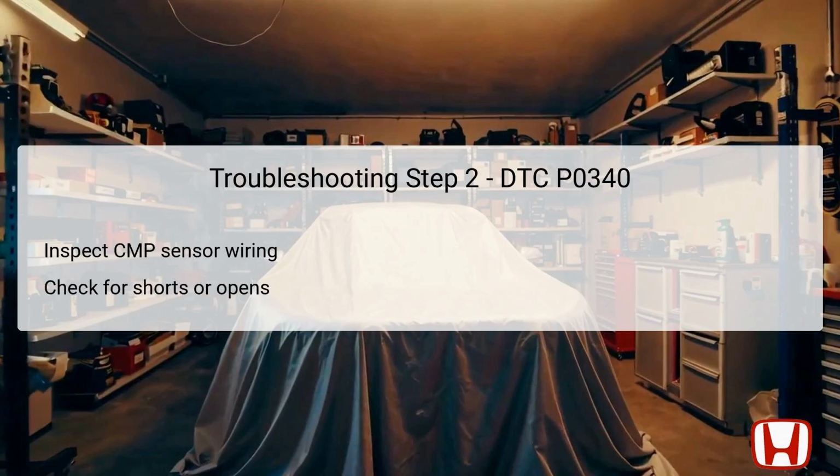The second step in troubleshooting DTC P0340 involves a meticulous inspection of the wiring connected to the CMP sensor A. This includes checking for any signs of shorts to ground, which can disrupt the signal transmission to the PCM. An open circuit can also impede the flow of signals, preventing the sensor from relaying crucial information.